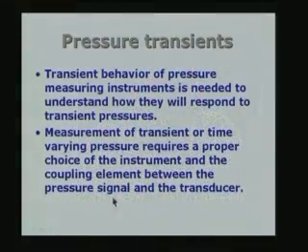So, we will look at some of these things in the present lecture. So, the nature of this response depends on... in the case of U-tube manometer, we are going to look at the various forces which are going to be coming into the picture and how the balance is going to be achieved. The important thing to remember is that the coupling element and the resistance of the coupling element is one of the important factors which is going to come into the picture.